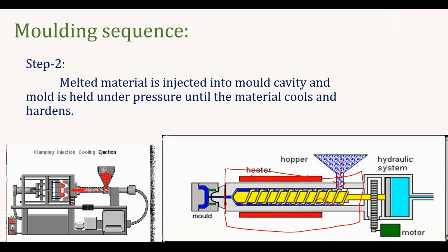This happens using a screw kind of arrangement, right? Generally we rotate this screw, and it makes the granules fall on the surface of the barrel. Whenever they gradually fall onto the surface of the barrel, they heat very gradually. That means uniform heating of the material will happen, and all the granular material will become molten.